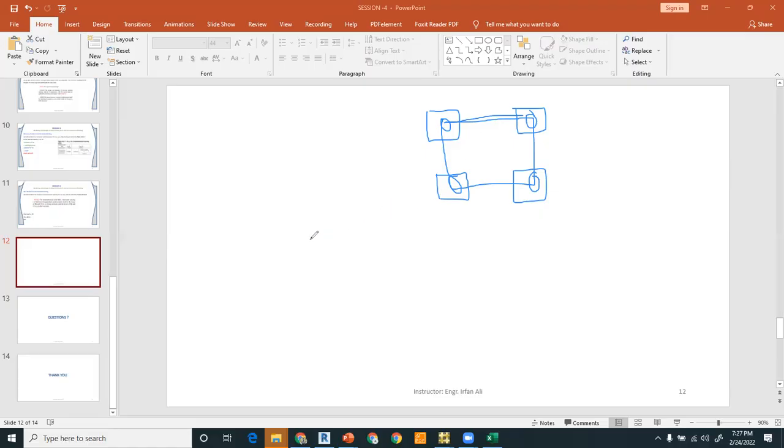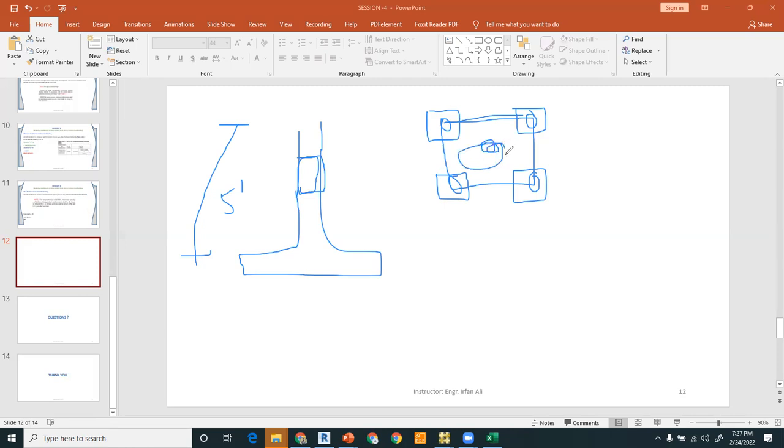दूसरा रीज़न ये है कि अगर आपके पास फिलिंग है, फॉर एग्जाम्पल ये आपके पास फुटिंग है, और यहाँ पे तकरीबन ये NSL है, और NSL से आप यहाँ 5 फीट फिलिंग करेंगे, तो फिलिंग के लिए ये अनस्टेबल बन जाता है। तो उसके लिए आप प्लेन बीम प्रोवाइड करते हैं ताकि ये इसको स्टिफ कर दे और फिर आप बीच में फिलिंग कर सकते हैं, तो दिस सिस्टम विल बी स्टिफ। तो ये दो रीजंस होते हैं जिसके लिए प्लेन बीम प्रोवाइड किया जाता है। ओके सर, थैंक यू।